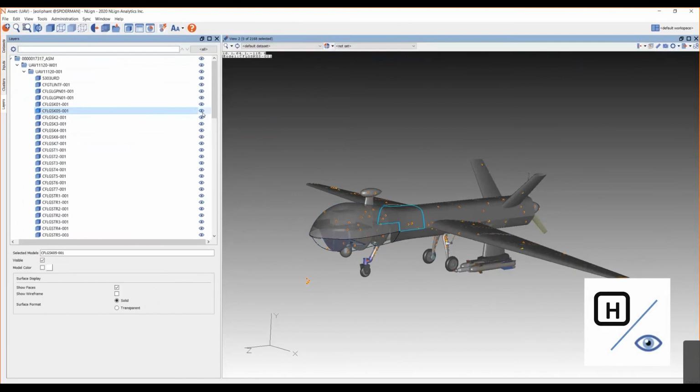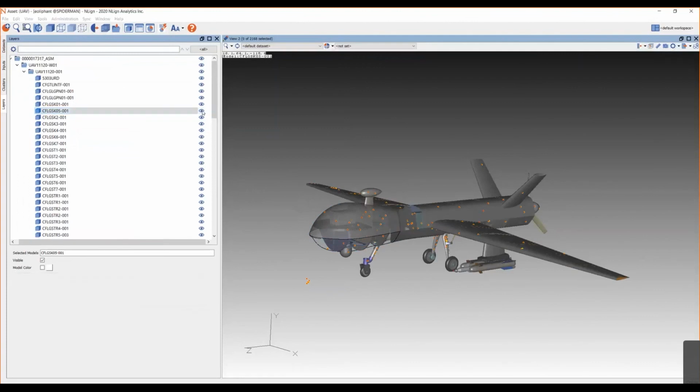I can toggle the visibility of the part with the H key on my keyboard. And you may notice this eyeball icon turns to eyelashes when I do that. I can click on this eyeball or the eyelash icon, and that will also toggle the visibility of that part on and off. Or I can hit the hide all models icon up at the top. Now that will hide absolutely everything. But if I click on the top level and then display the models as a solid, it'll bring everything back again.